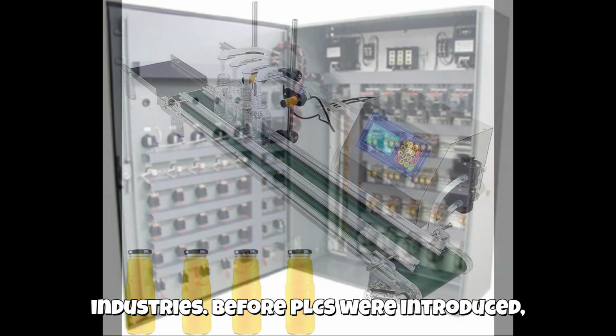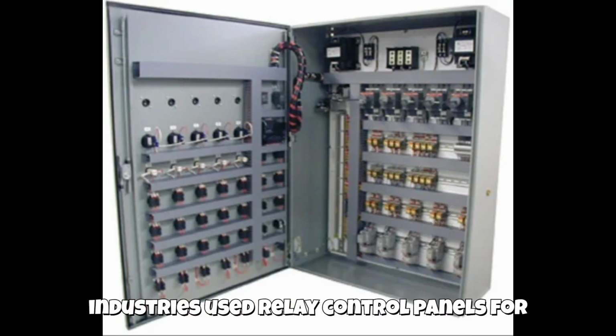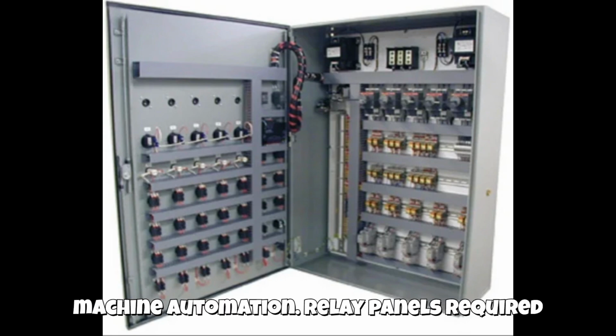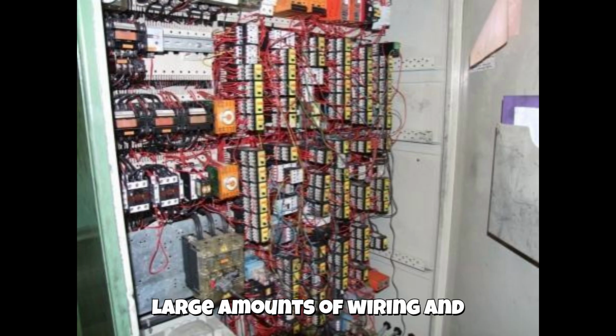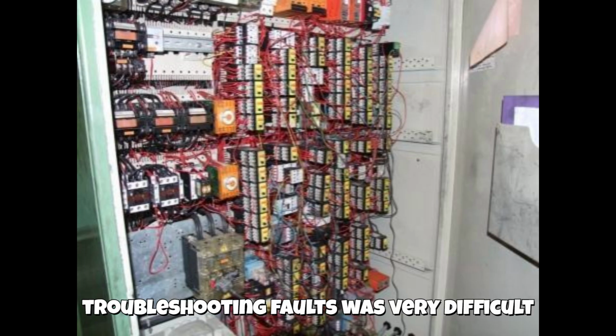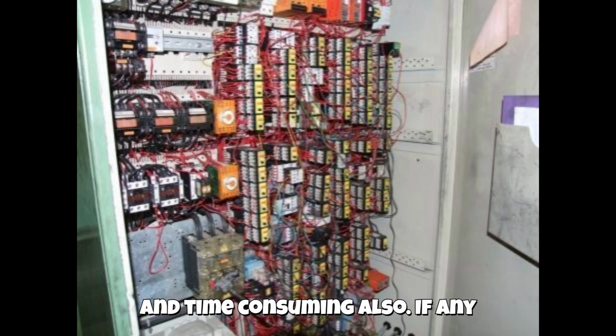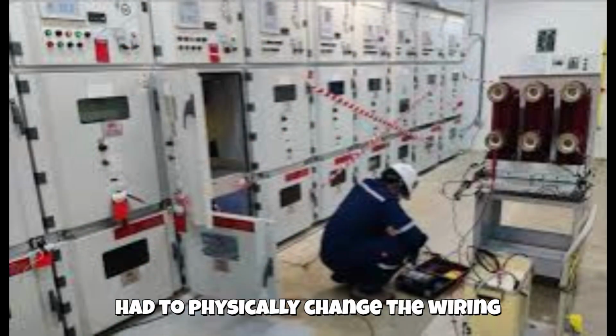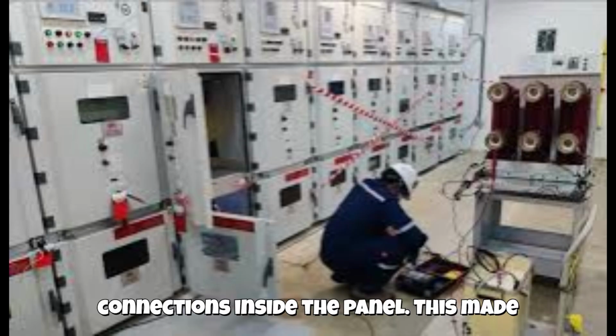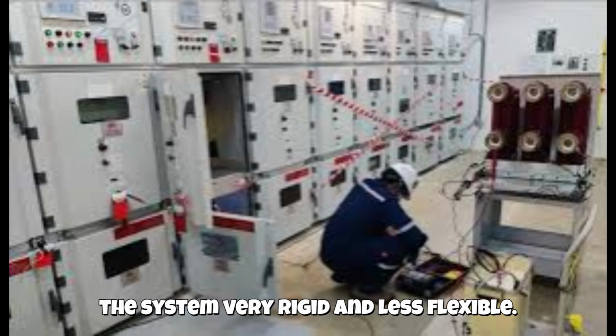Before PLCs were introduced, industries used relay control panels for machine automation. Relay panels required large amounts of wiring, and troubleshooting faults was very difficult and time-consuming. Also, if any change in logic was required, technicians had to physically change the wiring connections inside the panel. This made the system very rigid and less flexible.